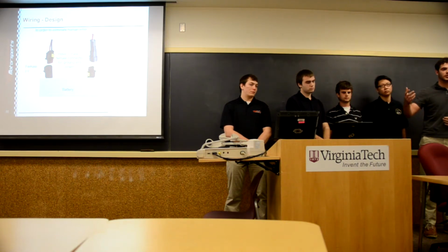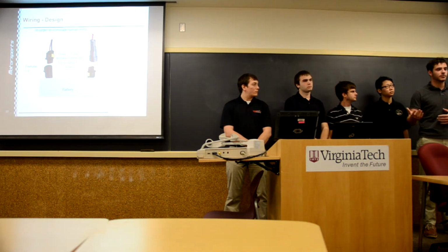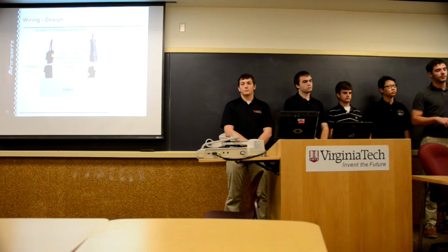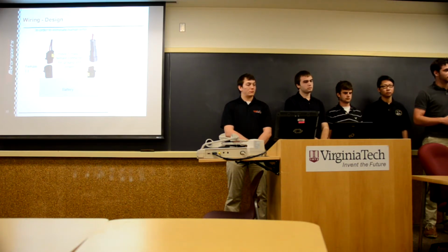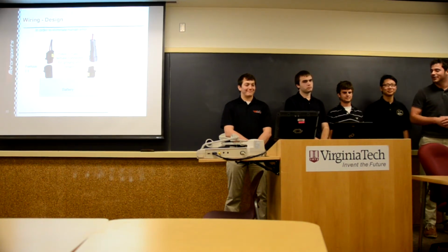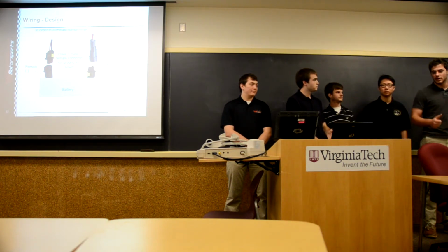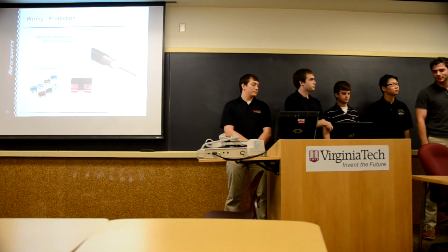Caroline's starting with just having different connectors. There's also the idea that, for example, on the battery, you'll switch the male and female connectors. So you have to put the male into the female for positive, and then the ground would be reversed, so you can't mix it up, which I heard there was one time there was a problem like that. So just to eliminate all human error, we're going to try to manipulate the system so it's practically impossible to mess it up.